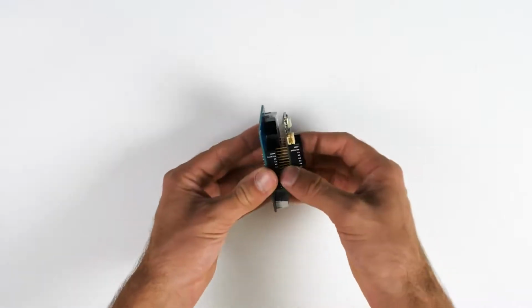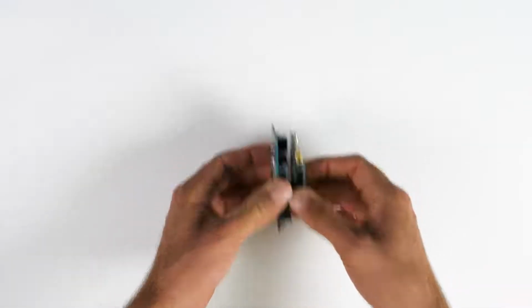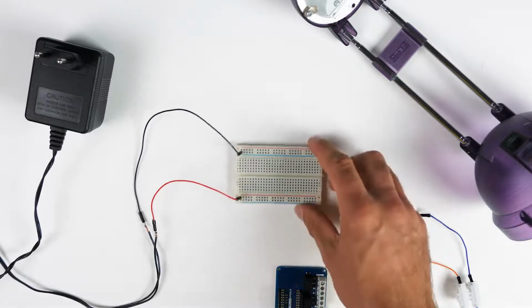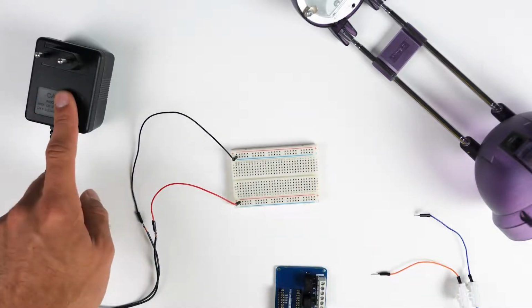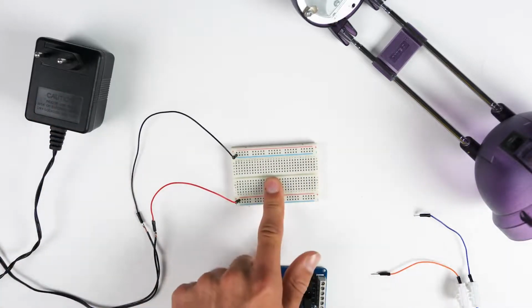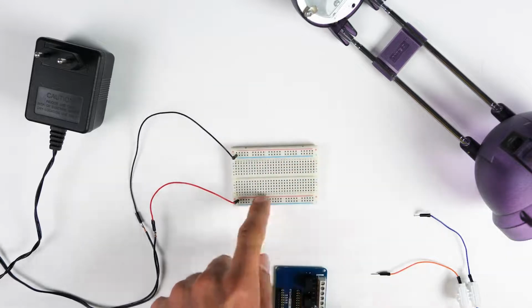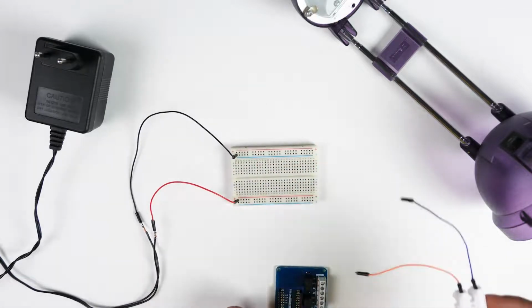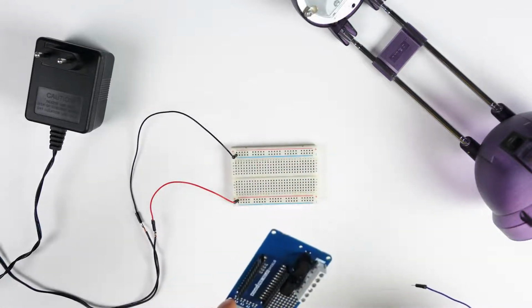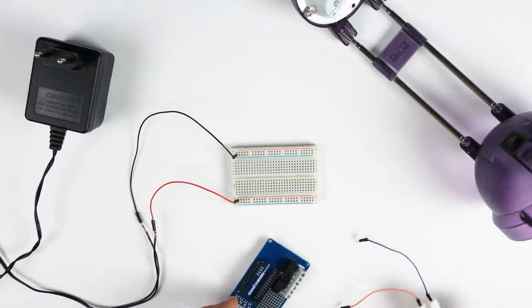The setup on the Arduino side is really easy. All we have to do is connect the Maker Wi-Fi 1010 to the relay shield. And here we have the setup. We have the power source connected to this breadboard, where we have the plus and the minus pole. Now we're going to connect this lamp to this relay and then to the power source.